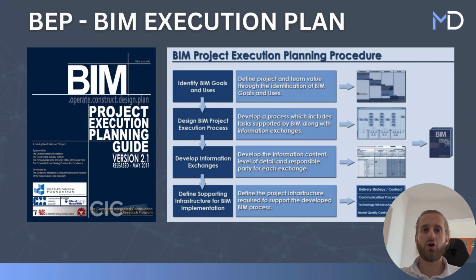One of the main problems with BEPs is that we should not decide every detail related to the project, such as specifics about suppliers, subcontractors, and so on. The BEP should be very concise and tailored to meet the investor's needs and requirements. Any BEP that exceeds 20-something pages becomes questionable as to whether all parties will read and adhere to it. Therefore, it should be concise and only contain the most important information to ensure smooth communication and properly defined model design and delivery.